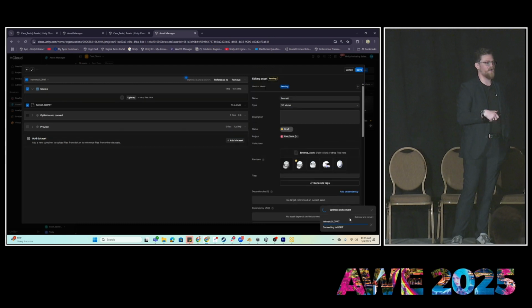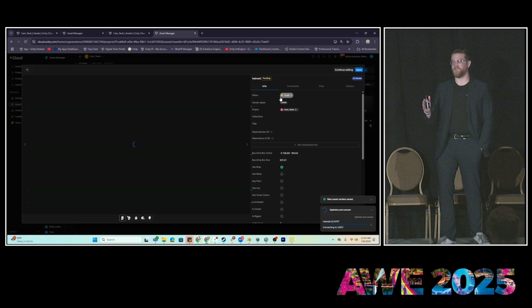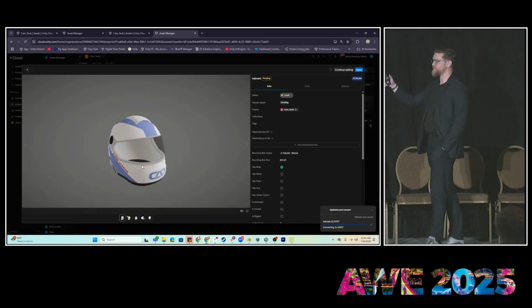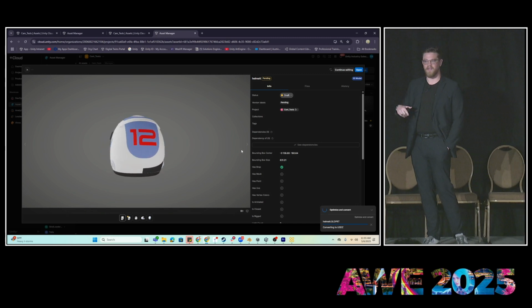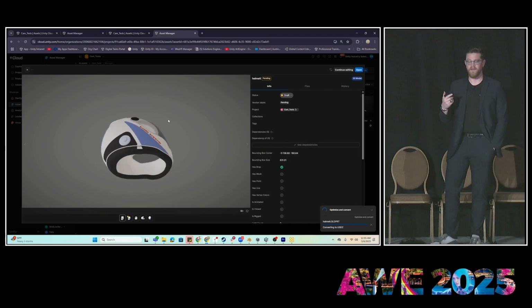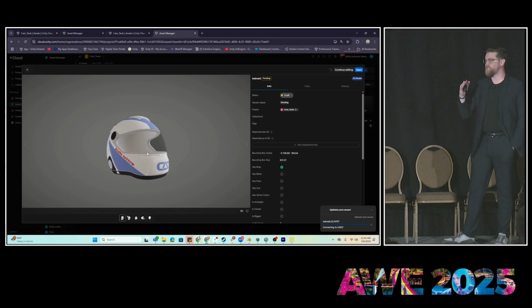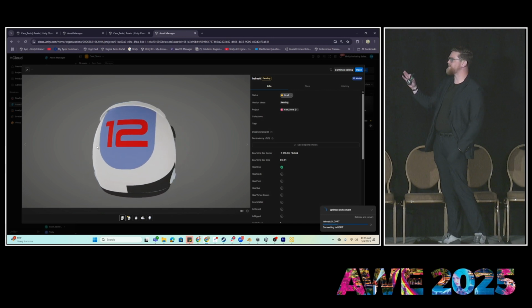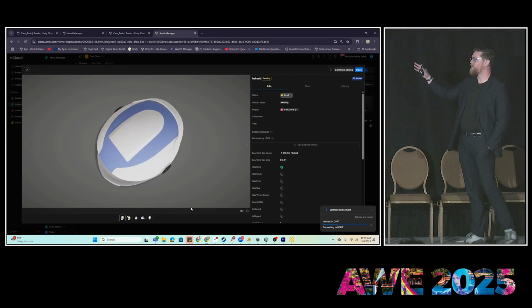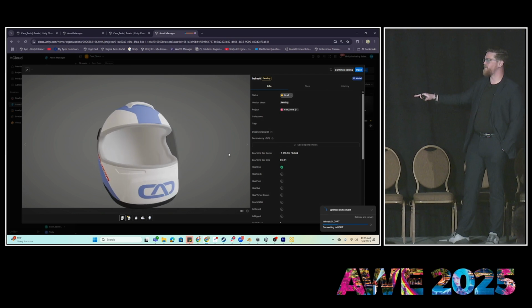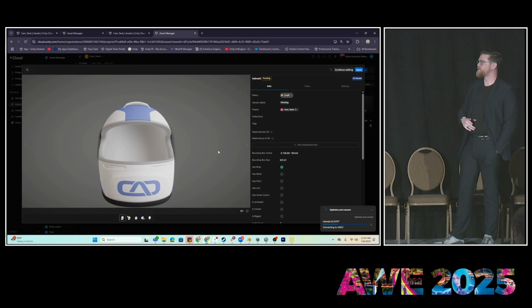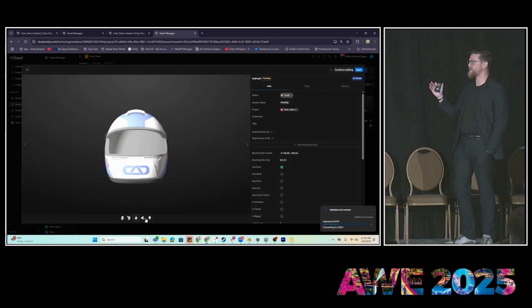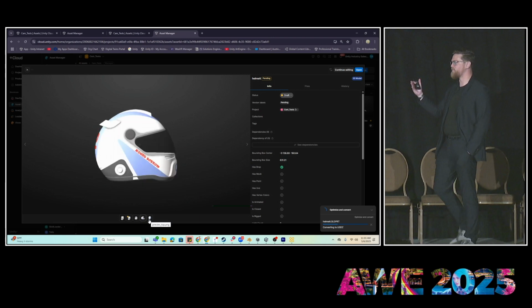While that's running in the background and doing all of that optimization and conversion for us, we can take a look at what came out of the initial upload process, which is this GLB file that my design team can now get in and immediately spin around and see what they do and don't like, and how it's changed from previous versions and iterations. We can also see that there's metadata and also PMI data that's been preserved on the right-hand side over here. So the beauty is that without anyone having to understand how to move from parametric to polygons, we can now get really nice, crisp feedback from the leads.